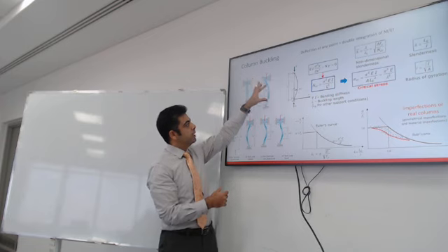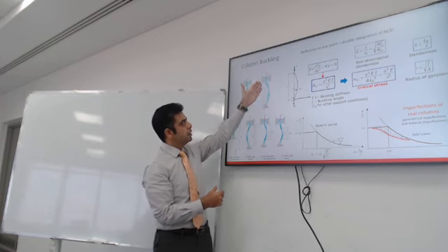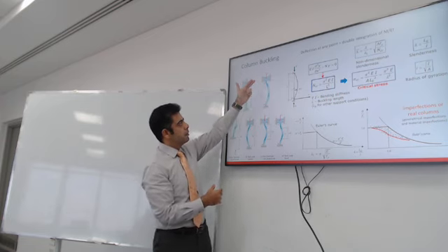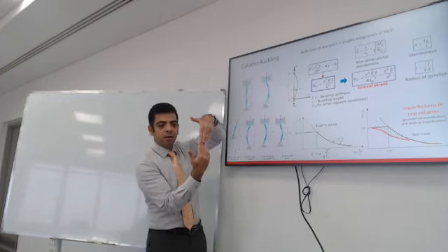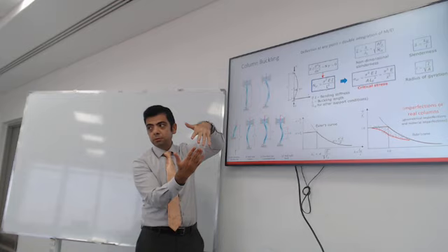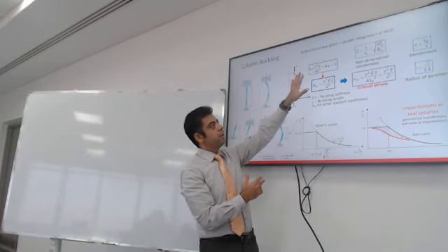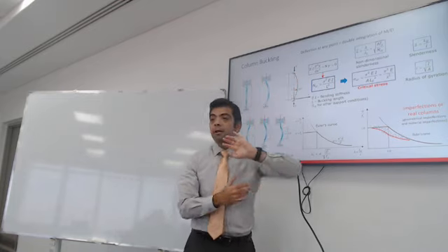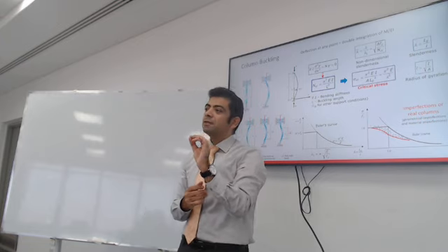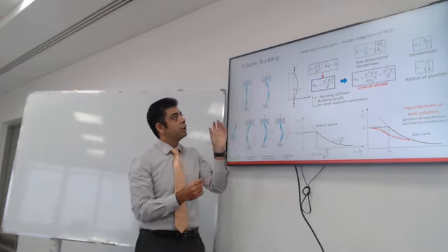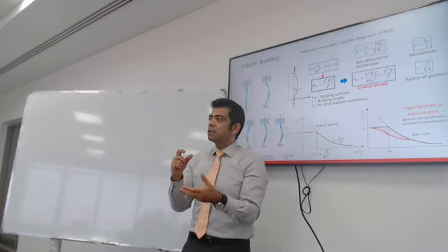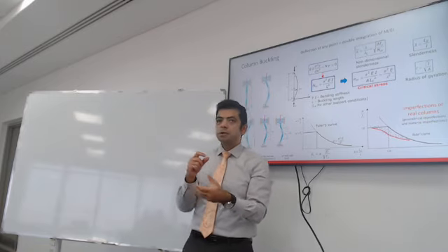So how do we get the load that will cause the axial column to buckle? We can do that from the equations we got in structure analysis. In structure analysis, we established that the deflection is the double integration of the moment.